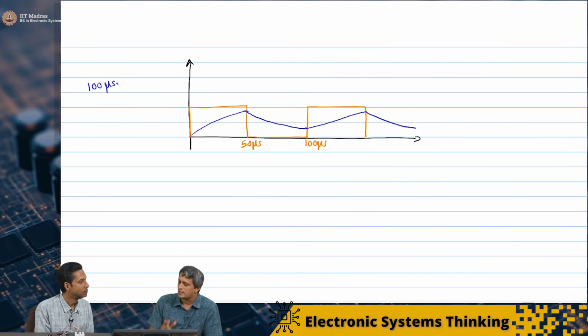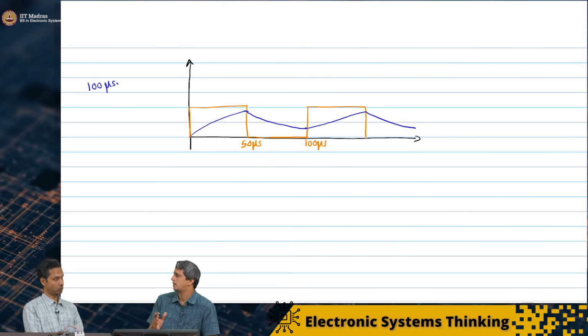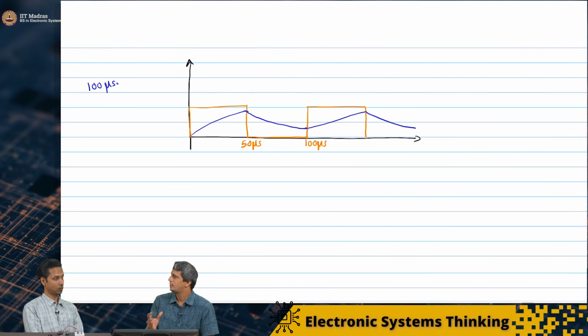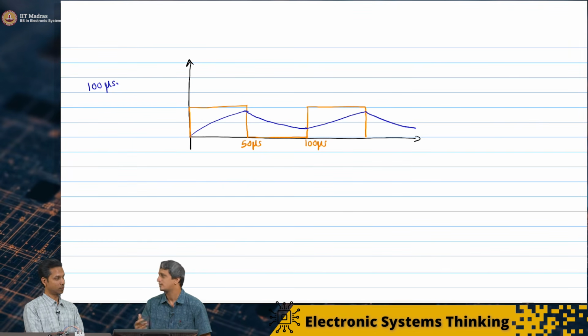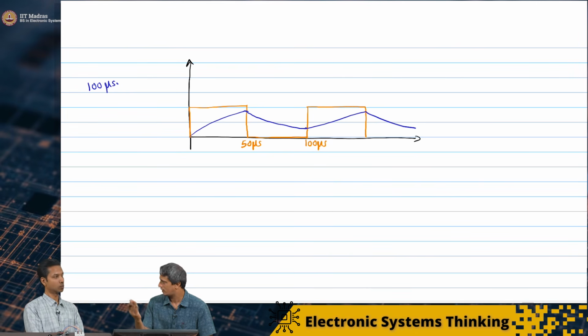But ultimately the key takeaway from the lecture today is that the time constant of the RC circuit is what determines the frequency analysis in general. There is a delay of the order of the time constant of the circuit, and therefore it's very evident now that if I have even one capacitor sitting somewhere inside my amplifier, the gain cannot be independent of frequency. It has to depend on how fast that capacitor can charge and discharge in order to give you that amplification.